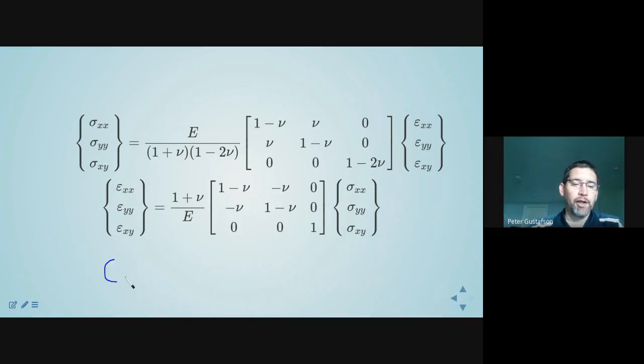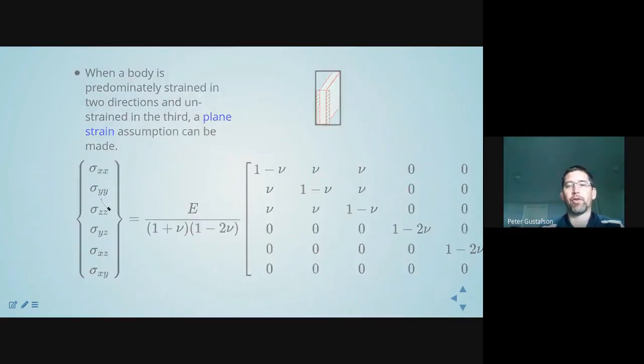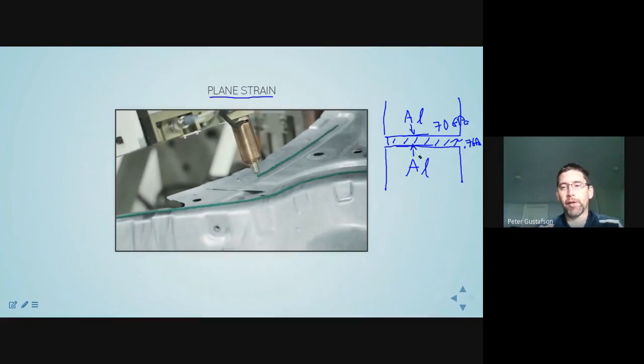Okay, I'm going to give you a big old caution here. This we have to do very carefully, and that's because the out-of-plane stresses in this plane strain scenario can actually be non-negligible. You can get out-of-plane stresses that are 20% or maybe even a little higher of the in-plane stresses. And so in some circumstances, if that adhesive happens to be particularly weak in that ZZ direction, you can cause that material to fail. In fact, in aerospace, one of the ways that the adhesives tend to be most susceptible to failure is actually in peel. So if you can get those materials sometimes to peel away from each other, and it delaminates, it can be problematic.